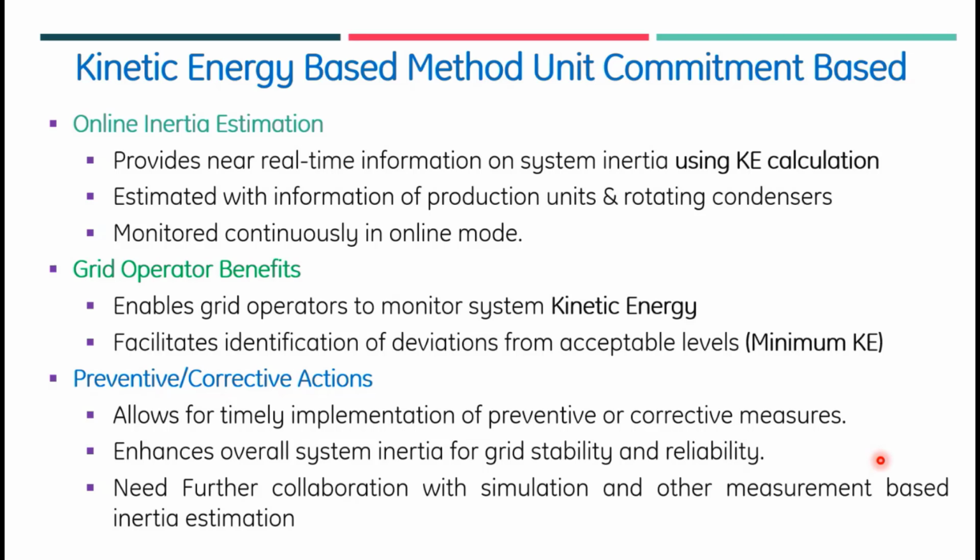So on one side you have inertia, and on the other side its current status, whether it is in service or not. And apart from that, the MVA, the capacity of this particular plant. So you already have the MVA and inertia, and whether it is in service or not. What you can do is compute the inertia by summation of each individual machine's inertia multiplied by its MVA level. MVA multiplied by seconds provides the kinetic energy stored in that machine. After multiplying each of them, you sum over the entire power system, over all available machines.